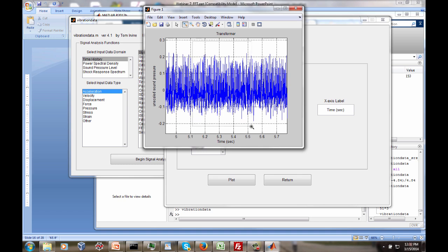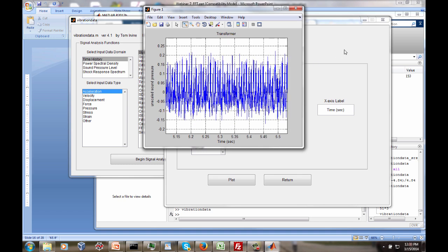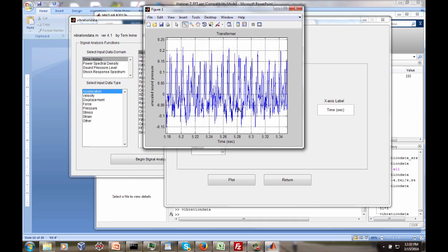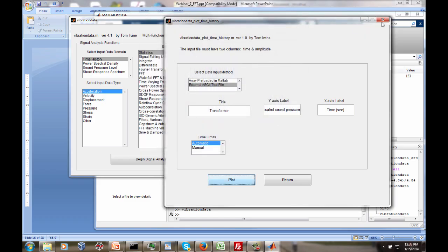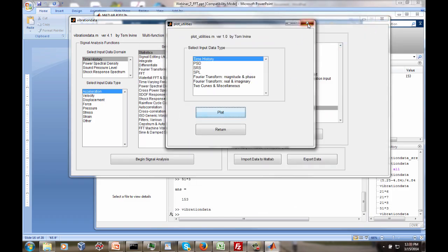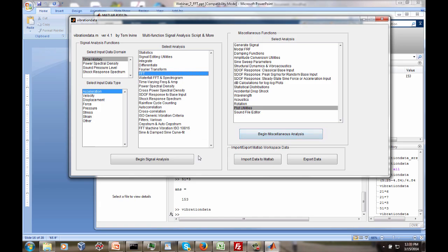And as we zoom in on it, is this random? Is it broadband random? Is it white noise, pink noise? Is it a damped sinusoid? Is it a beat frequency? Well, it does look like there's some repetition going on, so there's some kind of pattern. There's definitely more than one sinusoid, which actually we would expect, but there's some sort of repetition going on. So how do we resolve that repetition and identify those spectral peaks?